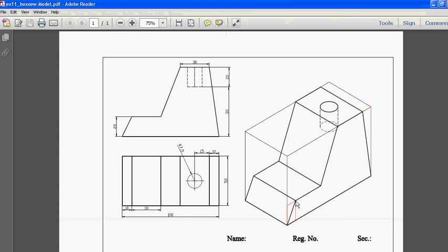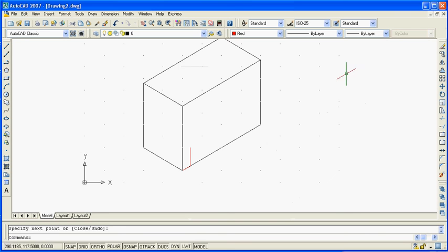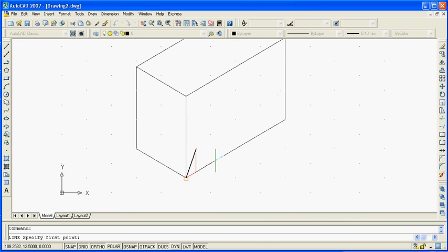This point I have drawn first. So from this point to this point I am going to draw a line. Going to a different line weight, I now select 40 and activate line weight. Go to the line command, select this point and select this point. The color I can change, select the color, by layer, enter. So I have done this line.